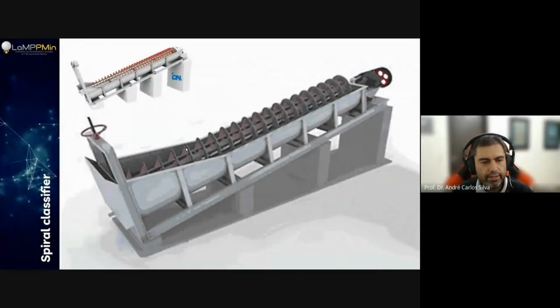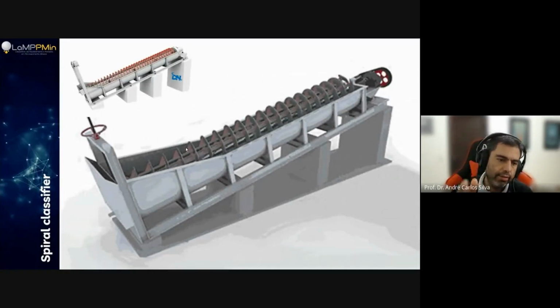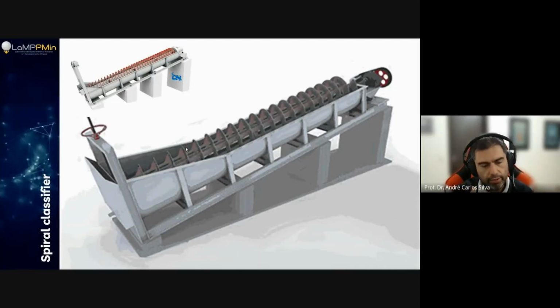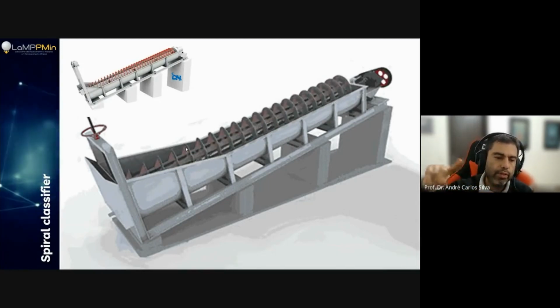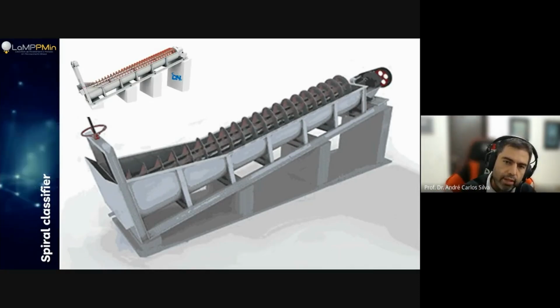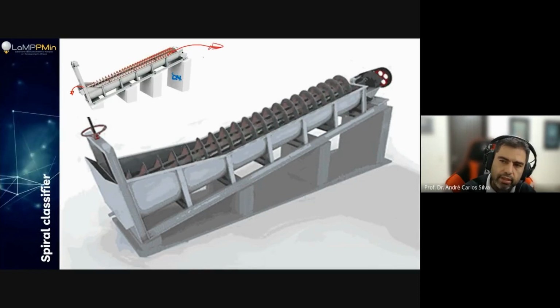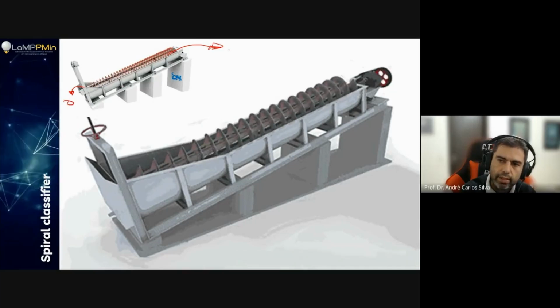That's the spiral classifiers. Now we're talking about water. You have to add water. So slurry goes inside this equipment and the material starts to sink. So the coarse fraction goes down. It sinks in the equipment, and this spiral just transports the material up. Okay, the fine particles are going to be dragged with the water and exit the equipment. That's the overflow of the equipment on this part. So the underflow exits the machine here and the overflow here. So here, overflow and underflow.